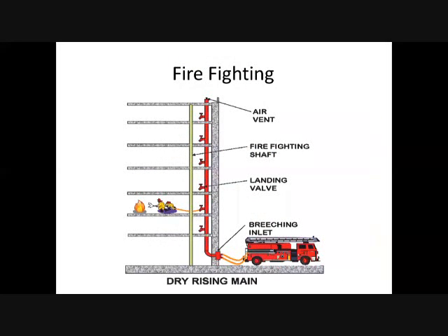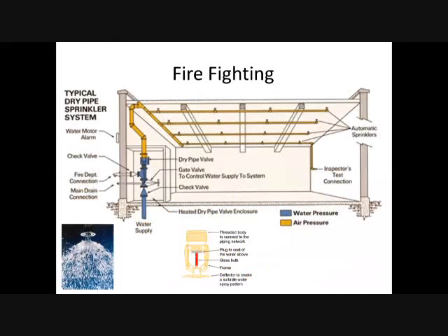The other system that is extremely important is firefighting, what you call FF. So for firefighting, we have to provide the fire brigade with an inlet of water. When they park their trucks, they have to have water pressure here to fight fires on different floors. So these are pipes that sometimes are empty. We call it dry riser. When the fire brigade comes, they connect to it and provide water. Sometimes these are continuously water-pressurized pipes. So you have to think also about the firefighting.